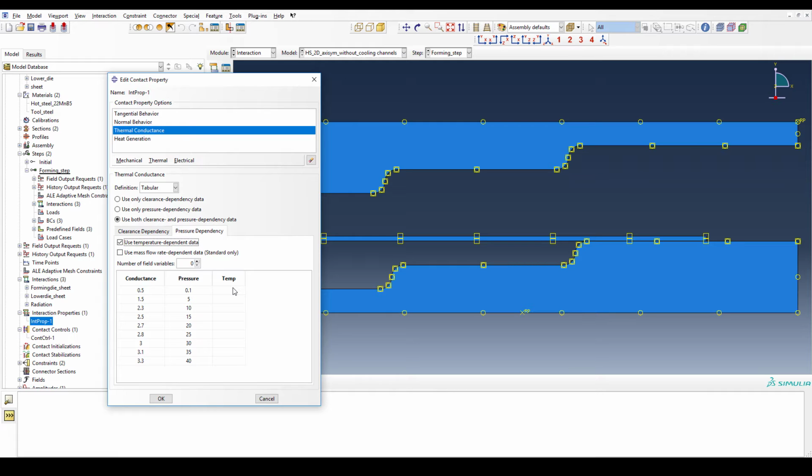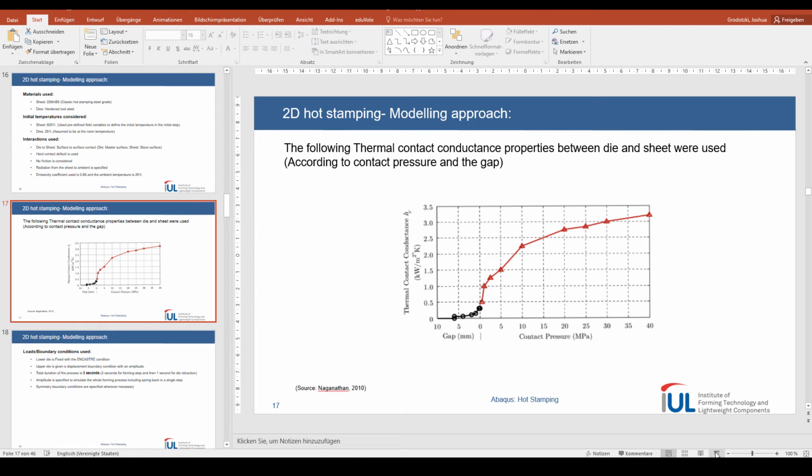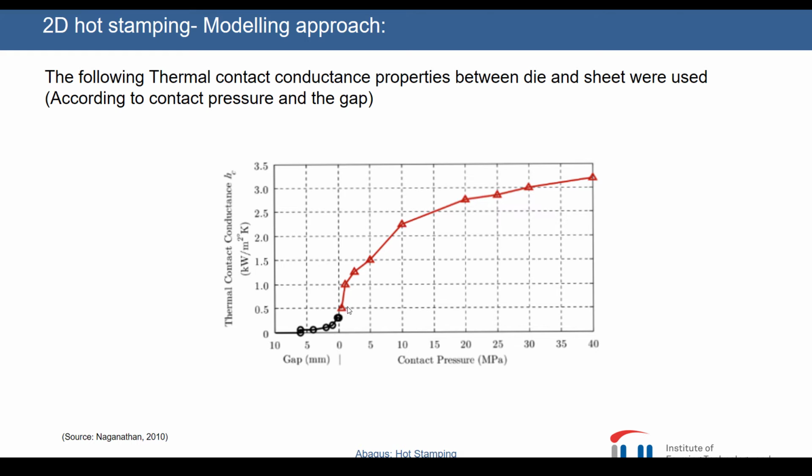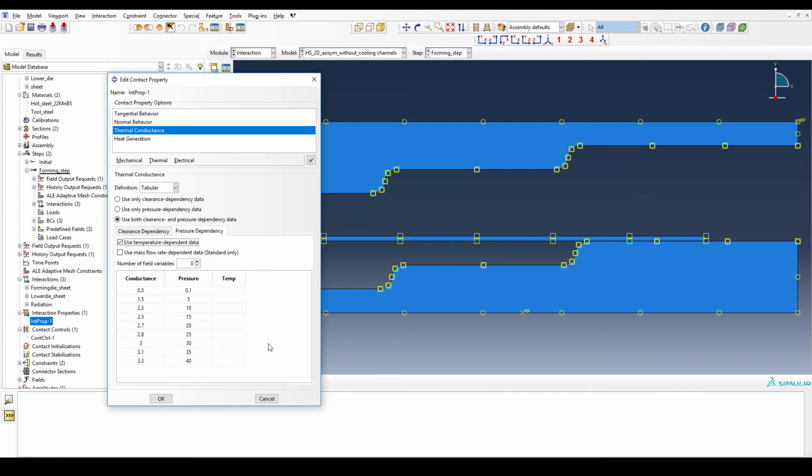To further improve on this regard, maybe we can switch back one more time to this slide here. So this curve could actually be temperature dependent. If we say this is for both bodies being at, let's say, 25 degrees, and you usually define it for both bodies being at the same temperature, it would look a bit different if it's at 200, 400, 600, 1000 degrees. So if you want to further improve the accuracy, you could include temperature dependent data, but you have to consider where this data comes from. Can you generate this data on your own?